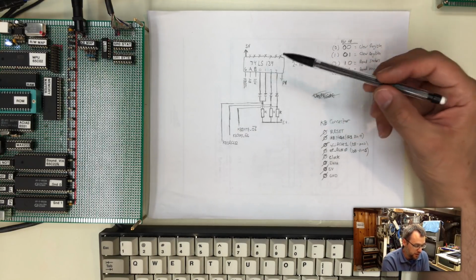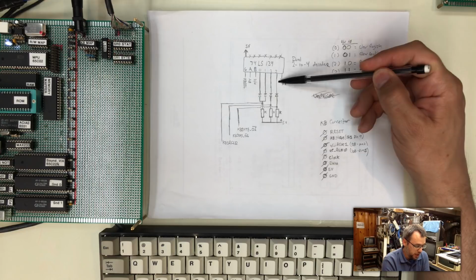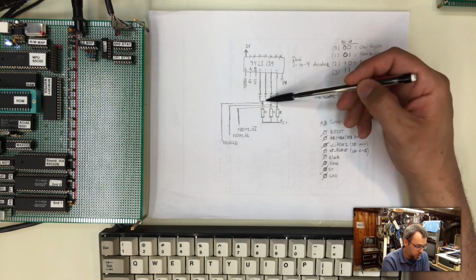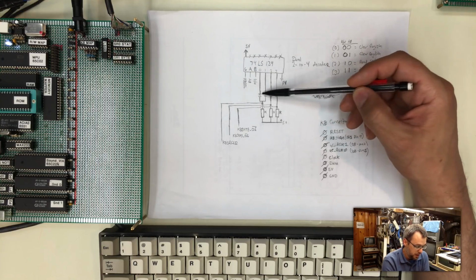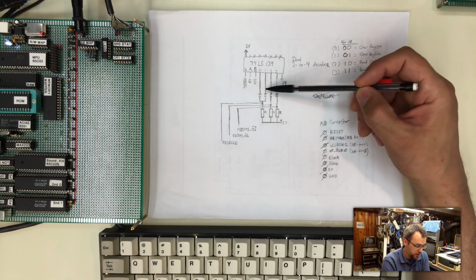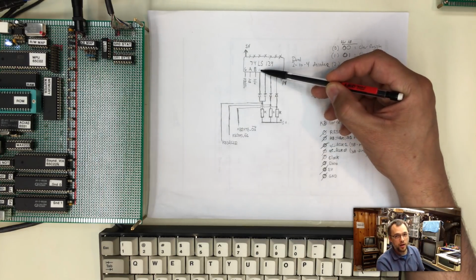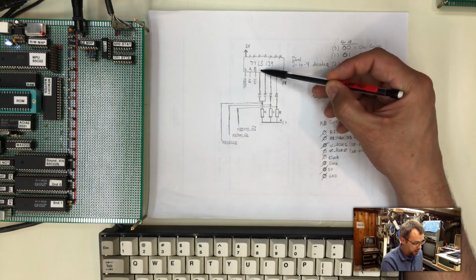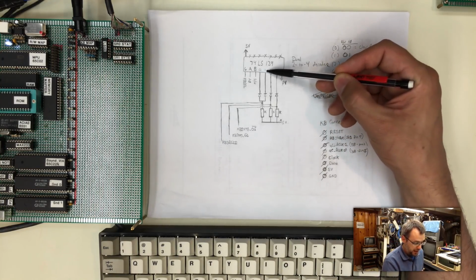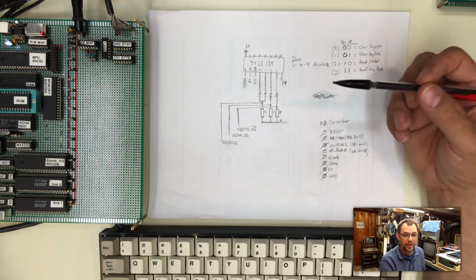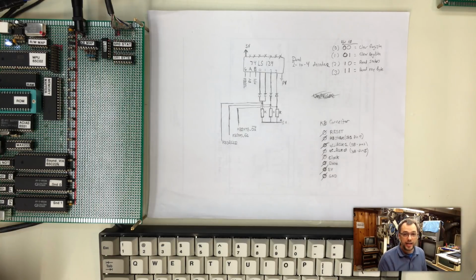So what we have here, though, are the address decode lines going out to our selection lines. Pins 0 and 1 are commoned together effectively to bring the keyboard SR clear. What this means is the 0 address here references writing to one of the status registers, and 1 references writing to the other status register. And as we remember before, I don't care which register I write to. If I'm sending a write command anywhere into the keyboard memory space, it clears the registers. That's basically all there is there.